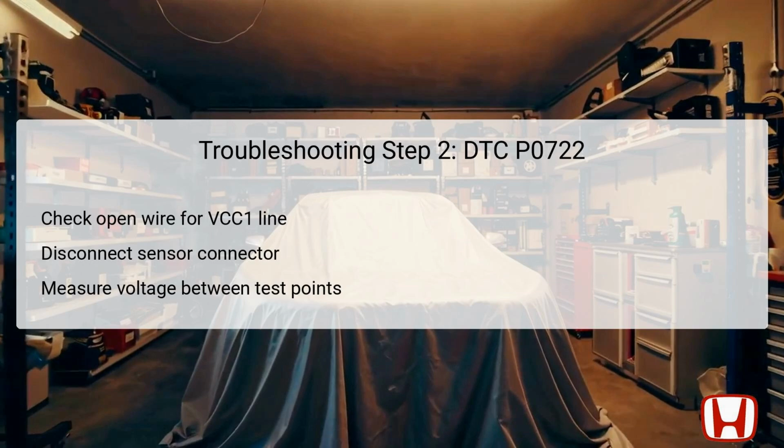For the second troubleshooting step, begin by turning the vehicle to the off-lock mode to ensure safety while working on the electrical system. Disconnect the output shaft countershaft speed sensor 3P connector, which is critical for isolating the sensor from the PCM. Next, switch the vehicle back to on mode to supply power to the electrical circuits.